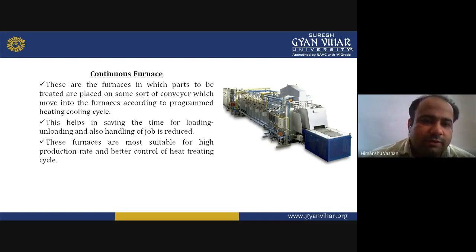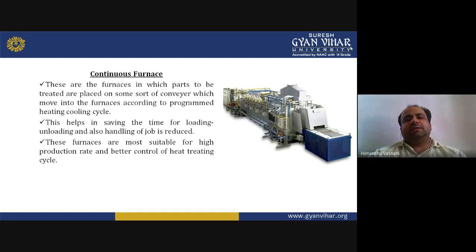Now the continuous furnace. This furnace is used in many industries nowadays because, although the pit furnace, bell furnace and elevator furnace can also be programmed, this kind of furnace has a good programmed heating and cooling cycle. Moreover, if you compare with the pit furnace, there is some time for loading and unloading of the workpieces.